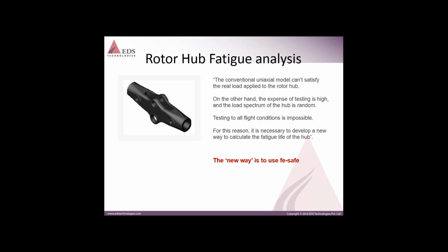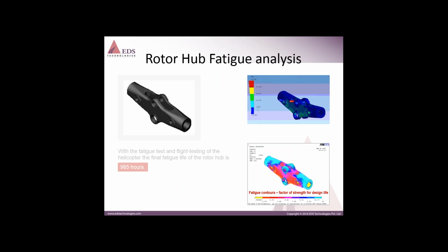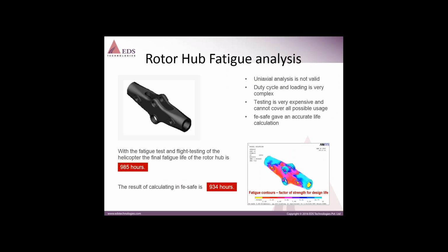The conclusion mainly from this type of analysis is that conventional uniaxial fatigue methods would simply not be able to cope with this complexity of loading. And also, multi-axial stress in this component and testing in flight is nearly impossible.